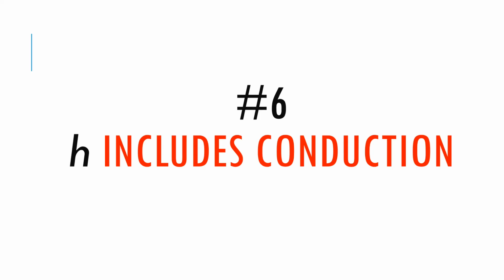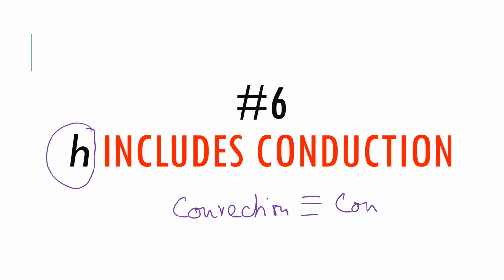So sometimes we have this confusion. We talk about conduction and convection, and h is the convective heat transfer coefficient. So is conduction something on top of this? Is it something separate? Remember, convection is conduction plus flow effects. Okay, so convection is flow added to conduction, and we're going to prove this by finding h for conduction only and compare that with convection when there is also flow.